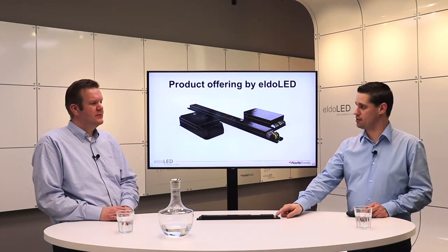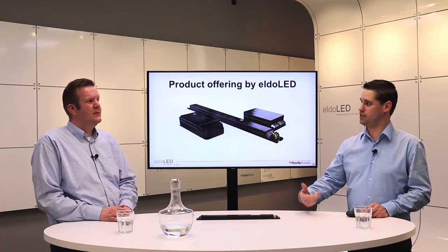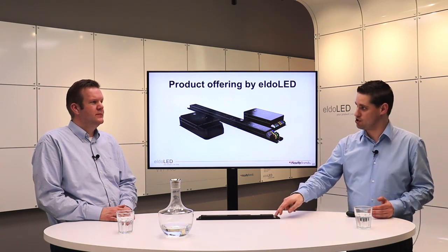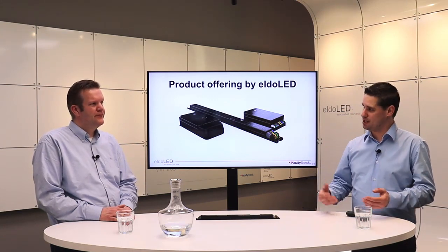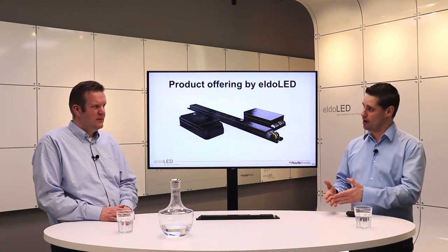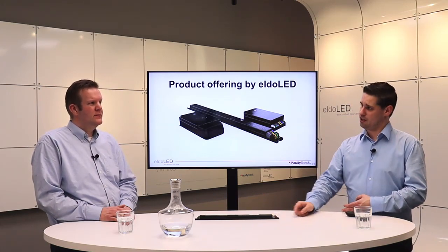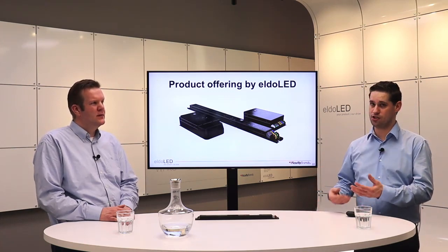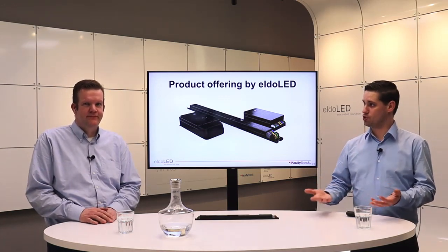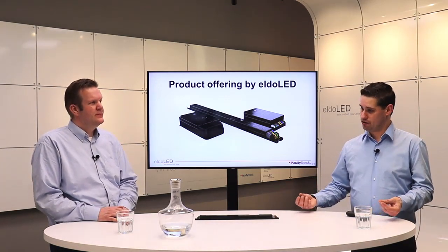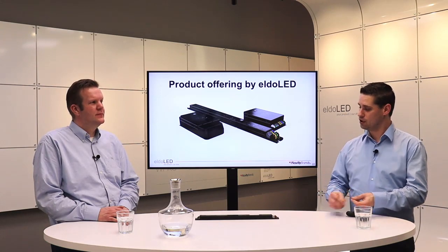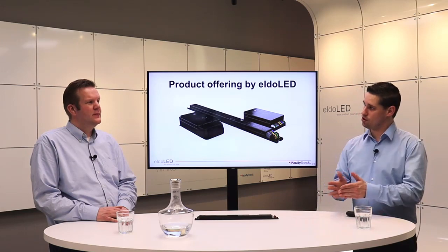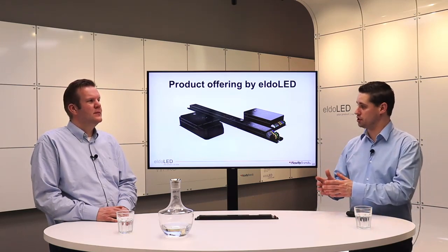For DMX, we have a 3-pole connector: the data positive, data negative, and the shielding. And because you need to daisy chain on the terminals, that might be a little bit tricky because you need to put 2 wires in that same terminal. A best practice there is to use a wire ferrule. So if you use a DMX cable, which is typically roughly 0.25 square millimeter, if you put 2 of those in a wire ferrule, you can still easily insert them into the DMX driver, and you don't have the issue that the cables might short each other.